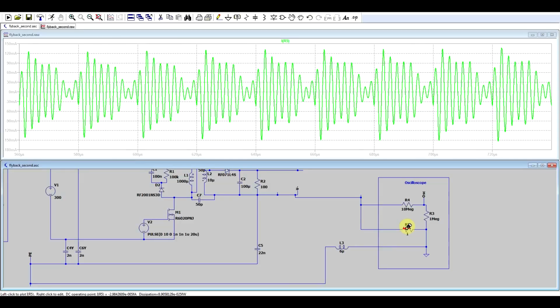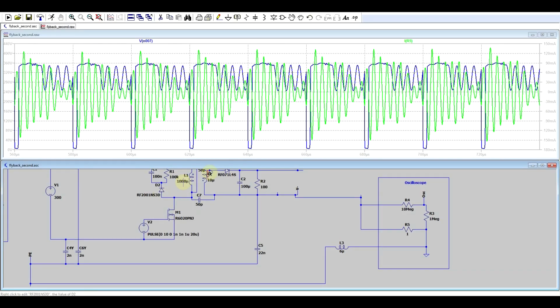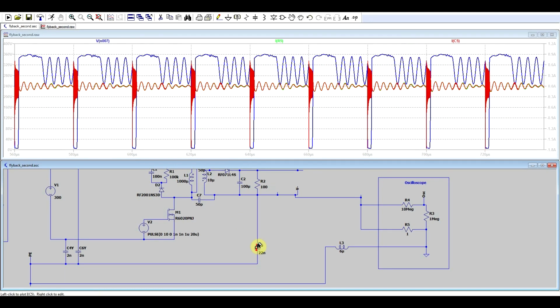So what we're seeing in the oscilloscope when we connect the ground is current coming from the supply discharging into the protected earth, and this is not something that should happen. This noise, this energy, is coming from the switching node, from the switching action of the supply, and this is coupling through the stray capacitance, and normally what would happen is that this energy would close back through the capacitors inside the supply.